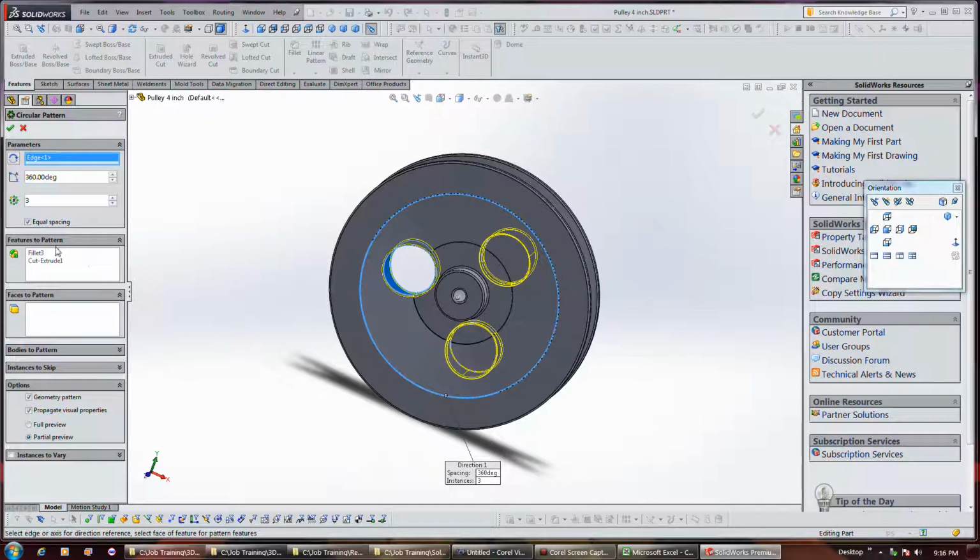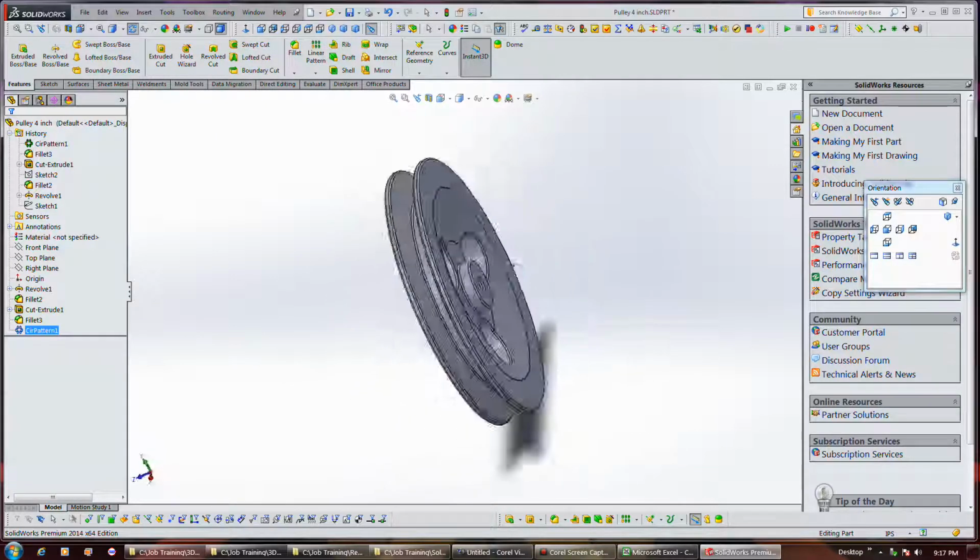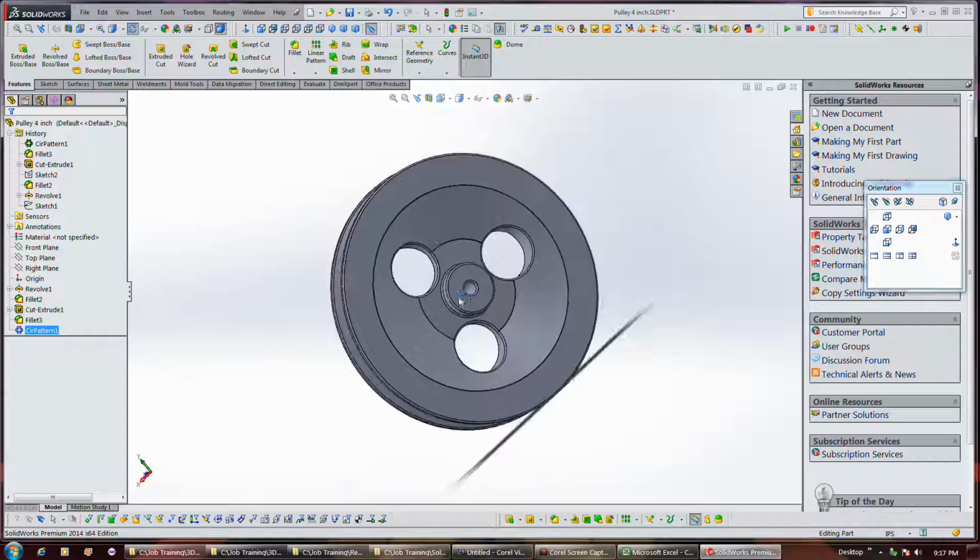Okay, when I'm selecting the orientation on this circular pattern thing, I selected this circle. So it acts as a guide, so that works. So you don't have to actually select an axis or anything necessarily.